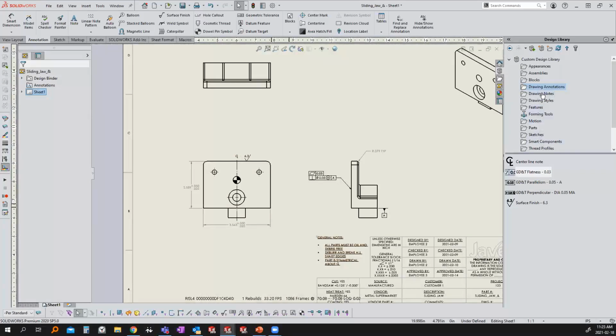All that is very easily accessible, and there's no typing things in. There's no mistaking my dimension tolerancing. I know, for example, trying to remember my company's specific dowel hole tolerancing from press fit to clearance to slip fit, I had to look it up many a time, and this just takes all that out of it.